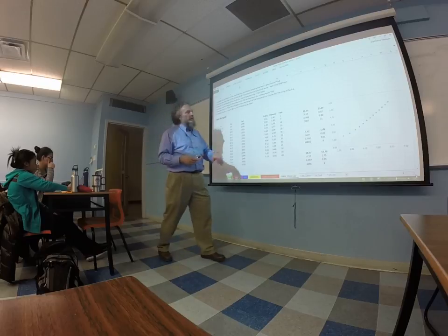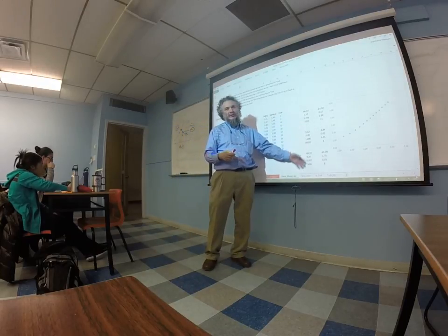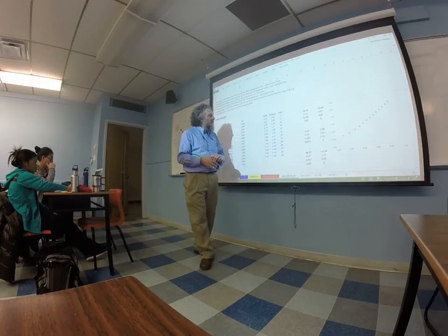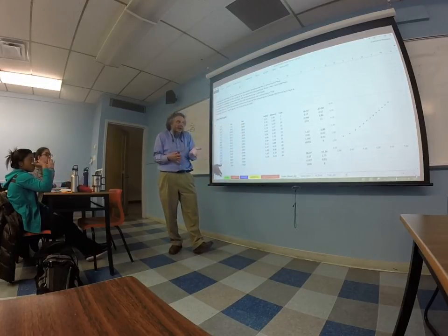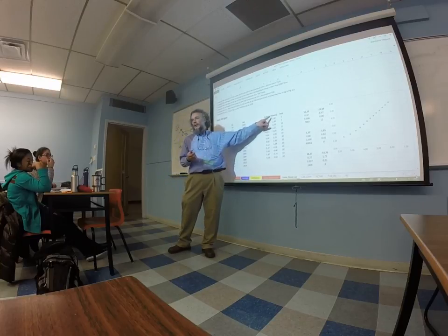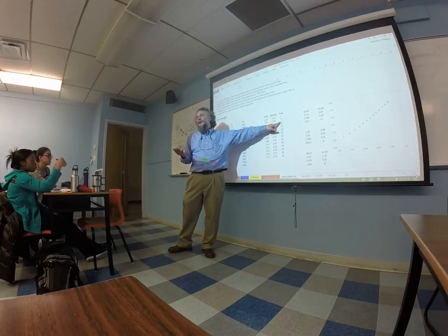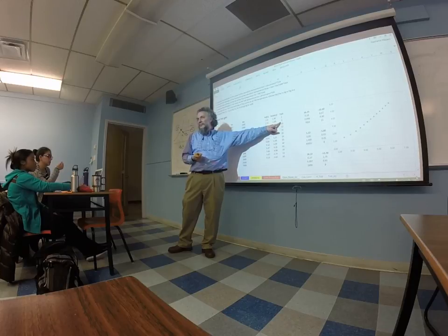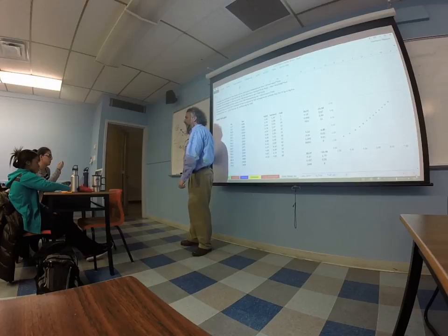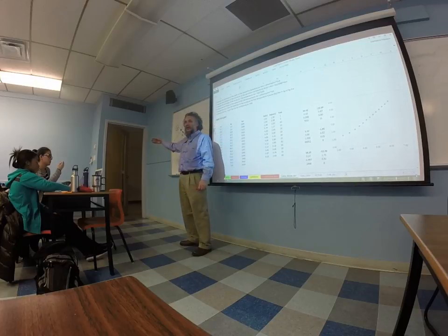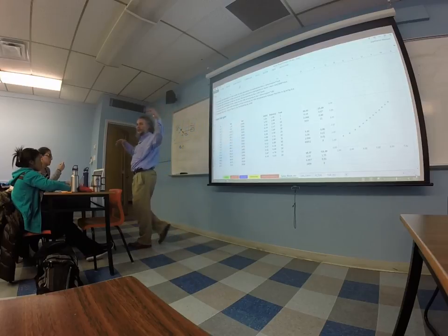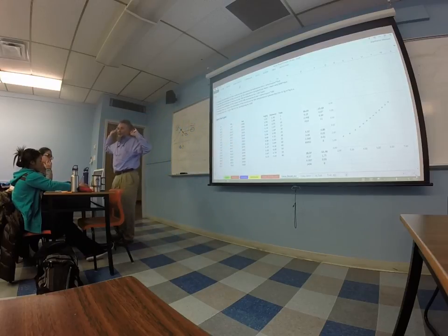So I did the three sort of correlations that these things could have, and the one that I ended up using was when I have the enthalpy and I want to find the wet bulb temperature, because that's the case that's more difficult. The temperature is everywhere in the equations, in the cubic, and in the exponential of the vapor pressure, and it's a pain to find.